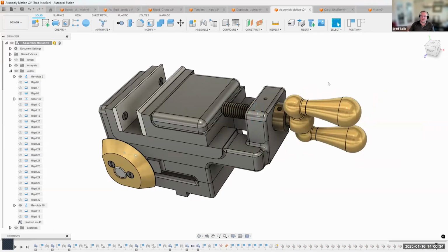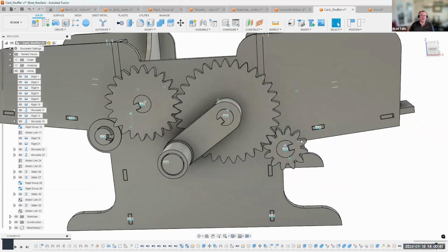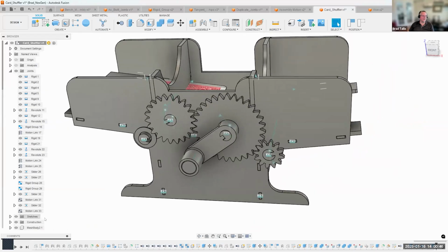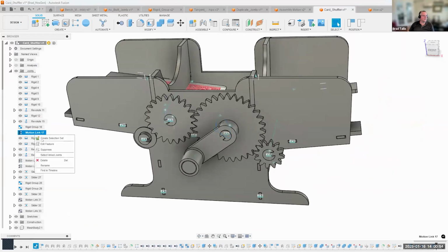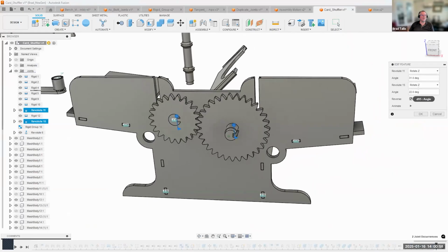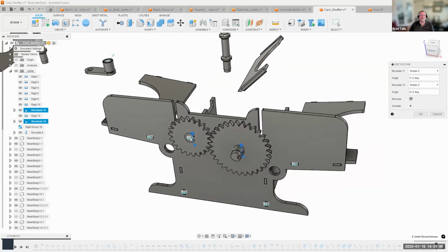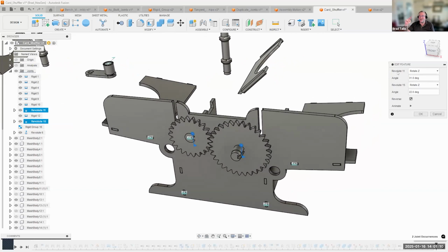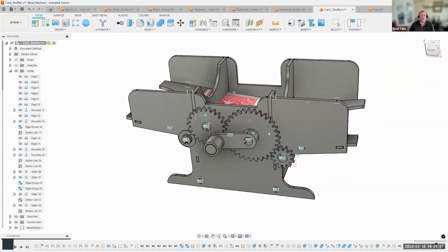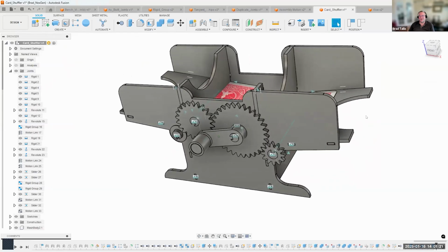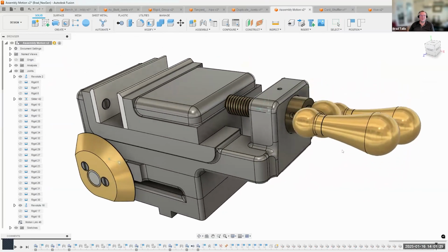With the gears, I was trying to show that, and unfortunately the card shuffler already has all of these joints, and I don't want to recreate them. But I basically count the number of teeth, and that's what you enter in for the motion link, the number of teeth. Let me do this one here. Let's see if it has it. Yeah, so 31 and 22. So there's a 31 tooth gear and a 22 tooth gear, and it's linking these two together, and that's what works for that gear ratio. I wish it even said, because it says angle, which doesn't make a lot of sense, but it's the gear ratio, and that's what makes that work. But yeah, it isn't smart enough to understand the pitch of that thread for this. So, good question though.